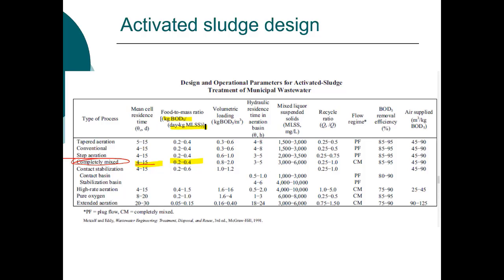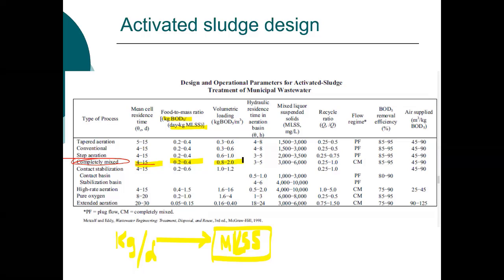So it's the mass of BOD actually per day. So if we're looking here at a reactor, it's the mass per day of BOD that's entering divided by the mass of mixed liquor suspended solids, MLSS, in the system. The volumetric loading is the mass of BOD per volume of the reactor.